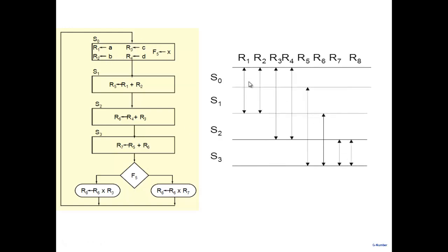Similarly, when I capture my problem in the form of a state-by-state description of how I'm going to execute whatever my system requires, I may be using more states than are necessary. I may be using a lot more registers than are necessary. I may not be utilizing the adders properly. So if you've just captured the problem, well, functionally it is correct, but it's time to examine also, can I share some registers? For example, if I just look at this one and draw a very simple picture, where do I find R1?